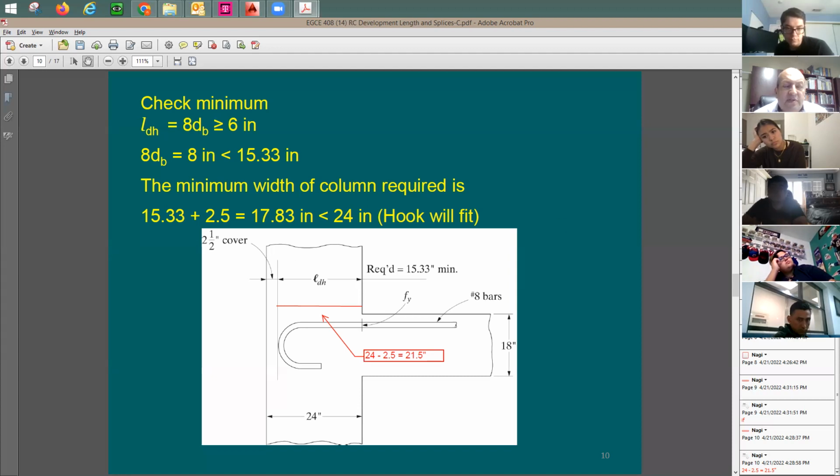Okay. In construction, the standard way of building this is going to be taking this rebar all the way to the end. It's just much easier for construction. If you give him a dimension like here and just keep it, let's say, to here. Let's say I am planning to do it like this, right? And bring it a little bit to the right. I brought this to the right a little bit, meaning give it more cover. Is this what you're saying?